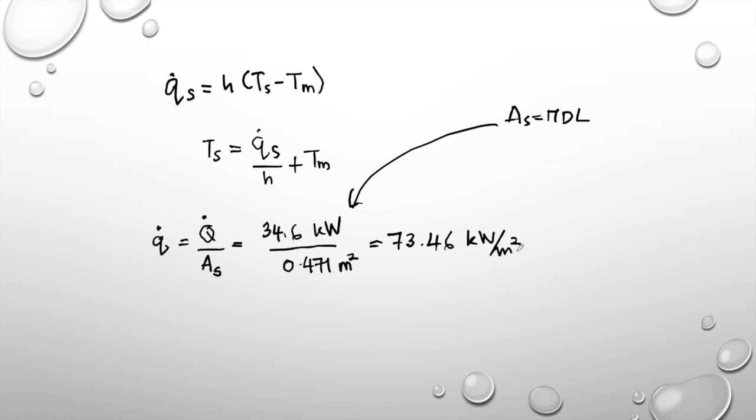So now we want to find the Reynolds number in order for us to determine whether this flow is a turbulent flow or a laminar flow. Then we can decide whether it is developing laminar flow, fully developed laminar flow, or fully developed turbulent flow. From the Reynolds number equation, V average times diameter, divided by kinematic viscosity.